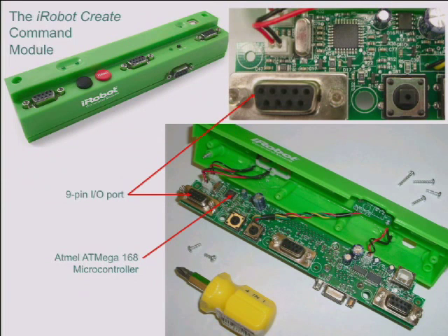But what if that code doesn't work? Actually, the code that writes to the serial port is pretty non-trivial. One of the project teams in that first year needed a second serial port so that they could have a Bluetooth connection along with the serial port connection. And they made a serial port out of a GPIO pin, which is a pin that you can, from the software, just tell it to be either high or low. Okay? And they wrote the code to turn that into a serial port. It took them an enormous amount of effort to do that.